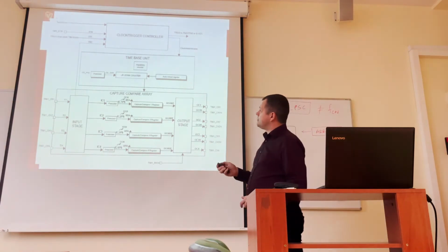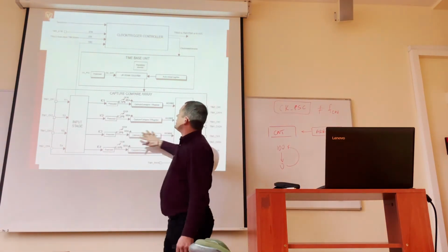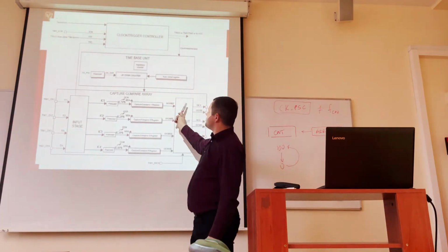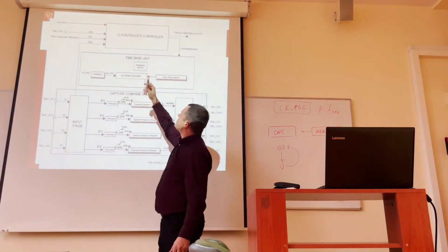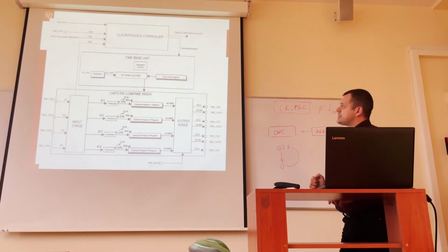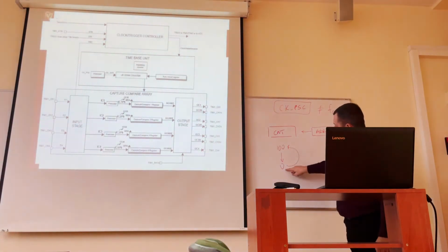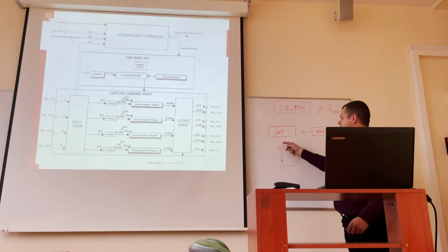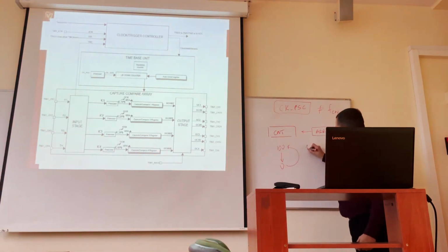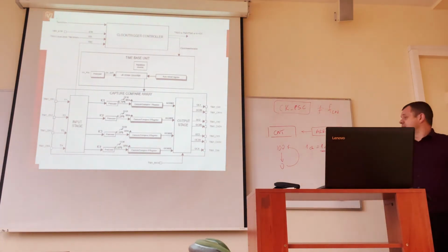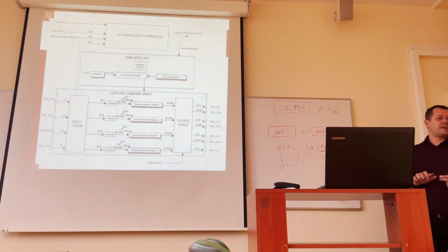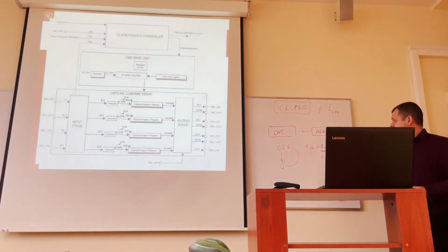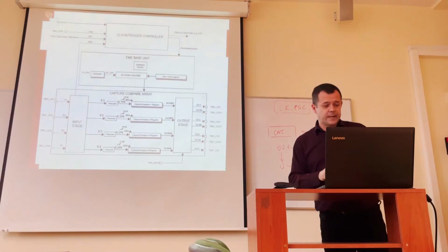This knowledge is really important, because of all these operations, and besides generating a time base, we don't need to use this capture compare array; we can use just this unit. It's not shown here, but we can generate interrupts out of this, for example an interrupt when it gets down to 0, and so have a time base. But we have to know that one clock cycle is, for example, 1 millisecond, and not, for example, 1.024 milliseconds, because as a time base that is useless, since then something will malfunction in our microcontroller.